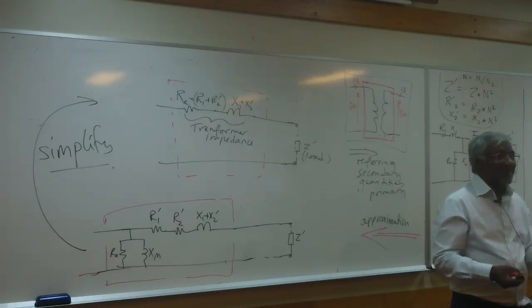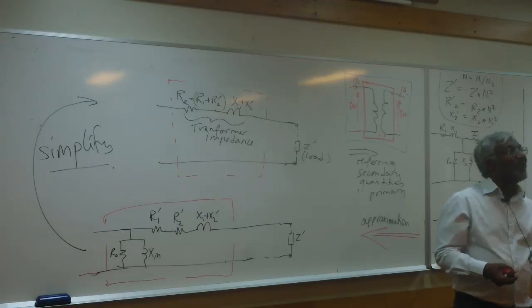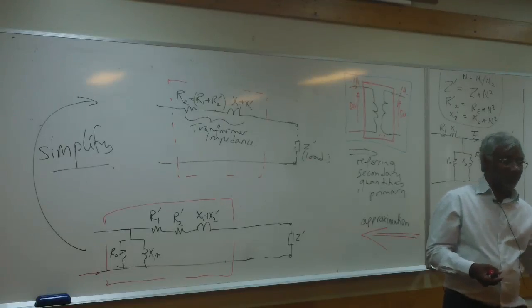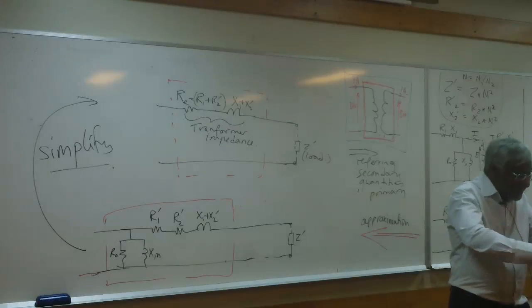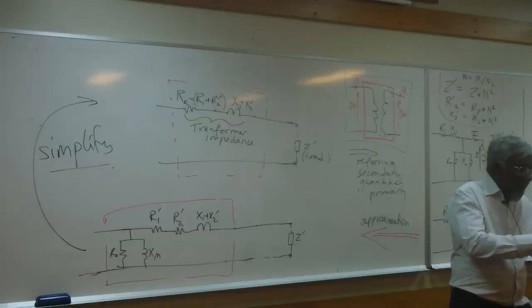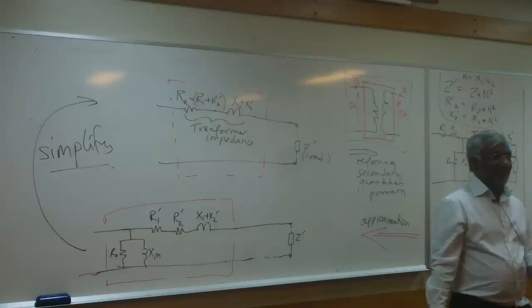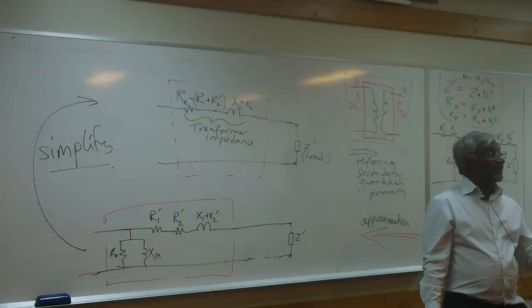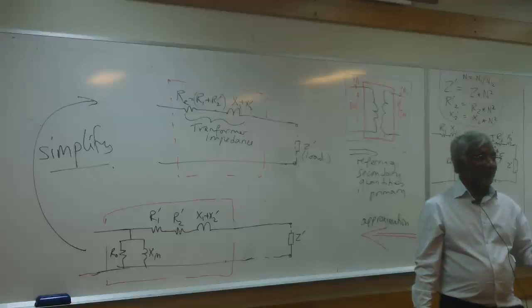The flux has to stay in the core. If you understand leakage, you would see why the toroidal core is superior to reduce leakage, why you have to have your winding uniform around the core, and why the bifilar winding helps you reduce leakage to zero. So if you don't like leakage, go bifilar and go toroidal.